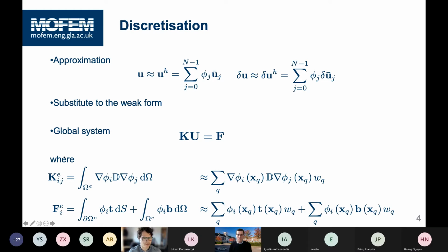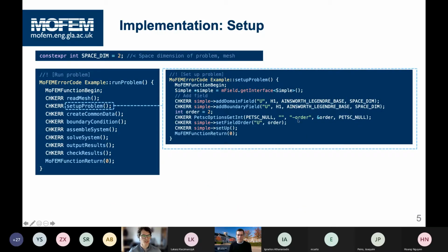The matrix is divided like here, and for the element vector, you can see below when we take the contribution of the tractions on the boundary and the gravity forces on the entire domain. And these integrals are calculated using Gauss quadrature, and in that form we can directly use them for our computation. So here we start dissecting the code.